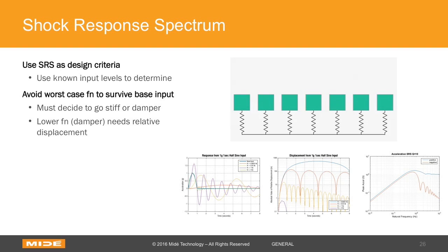The middle plot is important to look at, and that's the absolute value of the displacement that you get. If you look at the plot on the left, you think, oh geez, I want to be as low as possible. And that's true because you're dampening out the acceleration, but that 16th of a hertz spring has to withstand nearly 1,000 inches of relative displacement to fully dampen out that input. For certain applications, that is completely ridiculous.